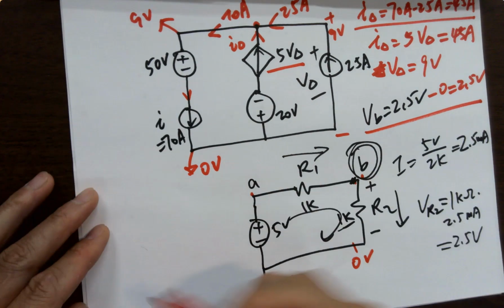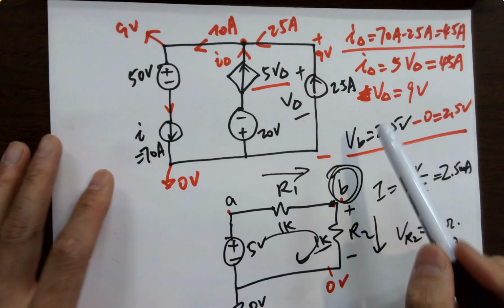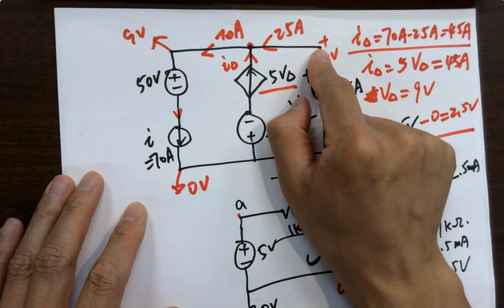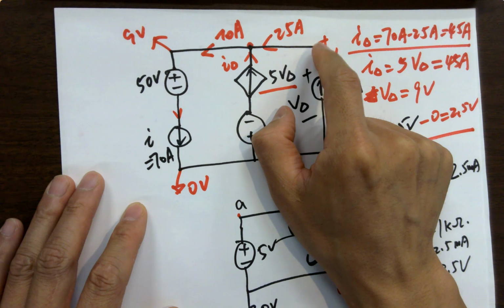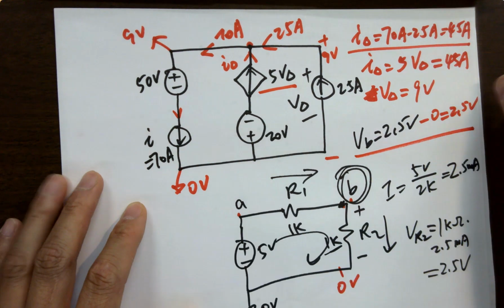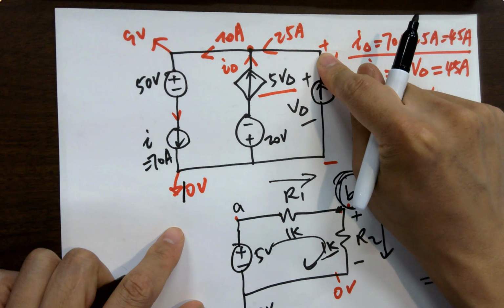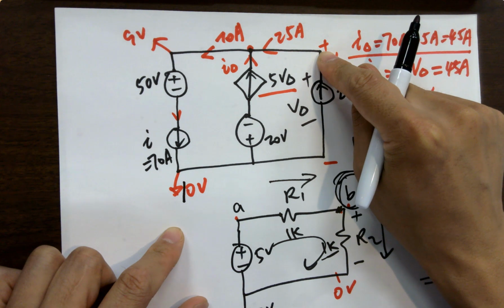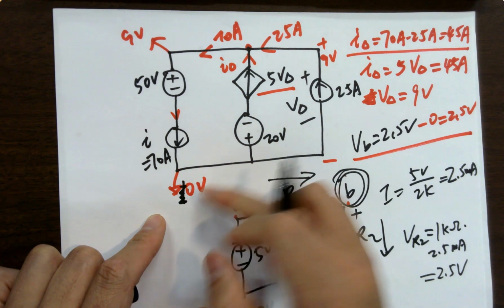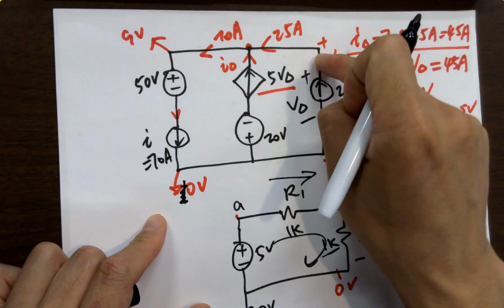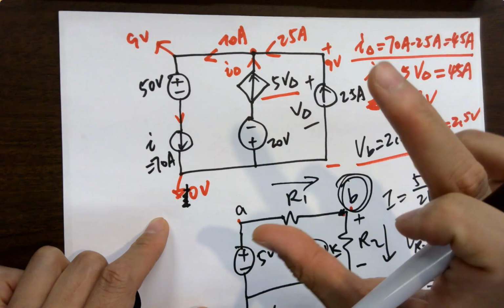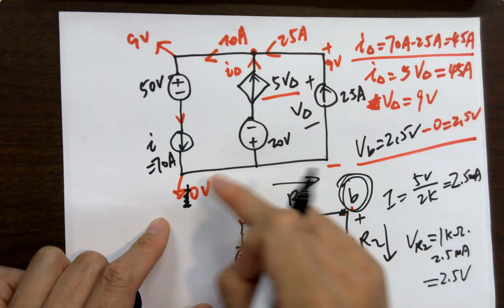Okay, now let's come back to this problem. So we have V delta is 9 volts. If I ground this point, I can directly say the voltage here is 9 volts. If the voltage here is not 9 volts anymore, it's 10 volts, what's the voltage here? 19 volts. Does that make sense? So now let's make it simple. Ground, 9 volts. I can directly point to a node and say the voltage at that node is something. Instead of always doing 2 nodes subtraction, I don't have to do that because I know here's 0.